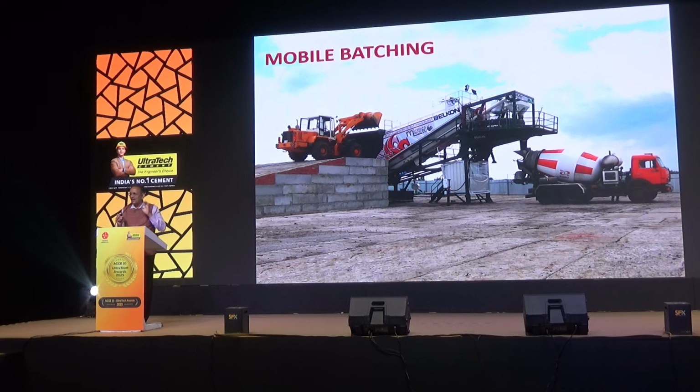Cubes should be tied to their parent element. Like if you are taking cubes for the columns, tie the cube to the column. And if you are taking cubes for the slab, tie it to the slab. And same with beams. So that the amount of curing you do to the slab or column or beam will be applied to the cube also, and the cube test result will reflect the curing also. I implemented this in some of the projects.